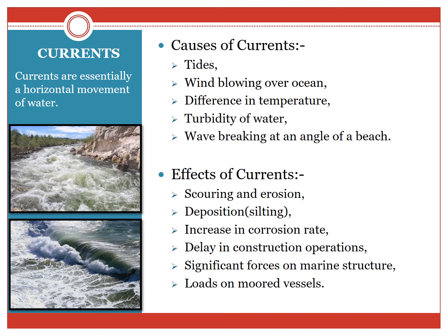Now, what are the effects of currents? It may be a cause of scouring and erosion to the seabed. Many a times, the silt deposition takes place. The currents are having a high turbidity of water, which in turn increases the corrosion rate.